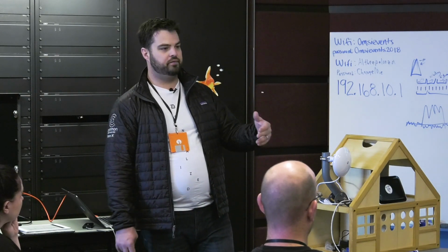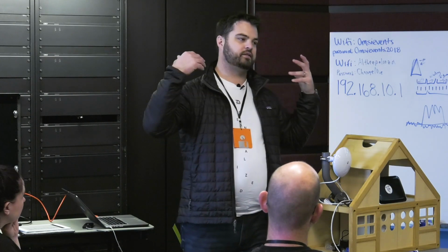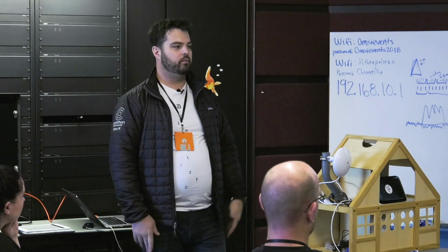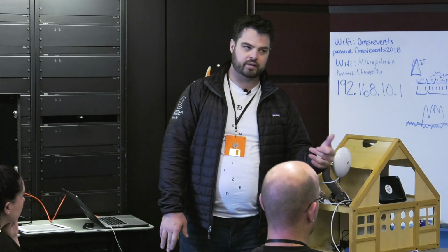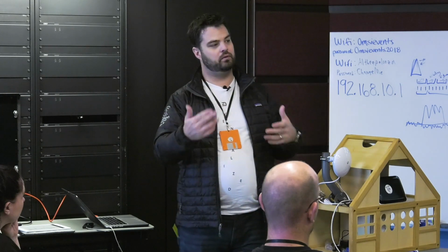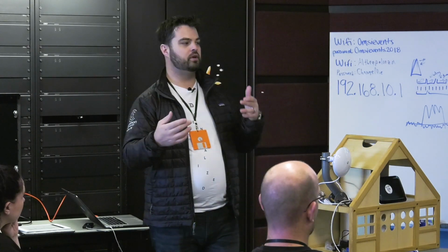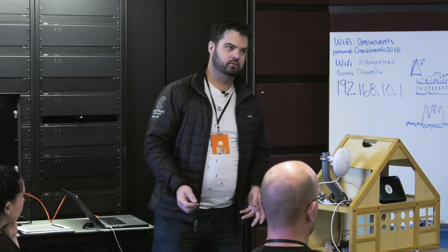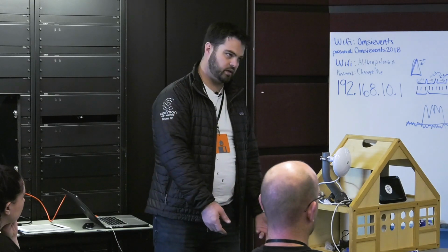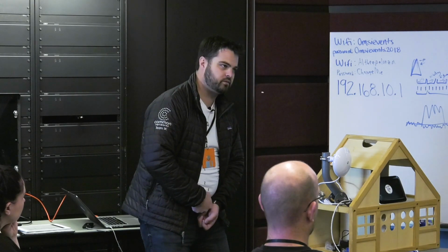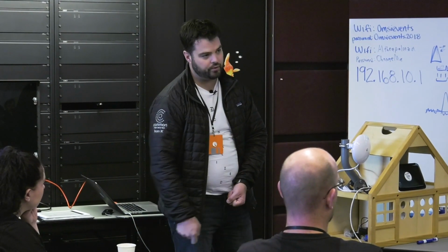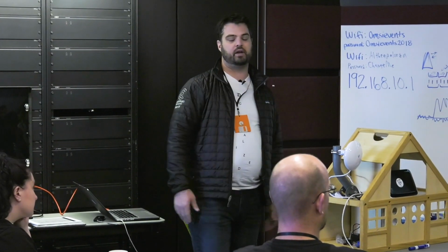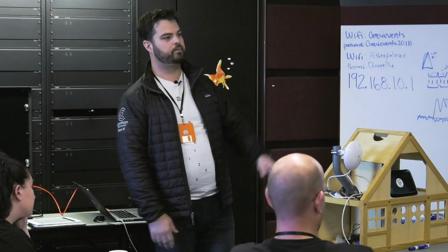The harder part is if you're climbing a tower and you bash your head on something or some ice breaks off up higher and hits you and you are unconscious, someone needs to rescue you. You should always have 2 people working on the tower at any time, and you should both know how to rescue the other person safely. Briefly, the rescuer climbs the tower to above the unconscious person, comes down to them, hooks themselves to that person, cuts that person off the tower, and then descends to the ground. To get certified, you have to practice that. You have to both be rescued and rescue once a year.